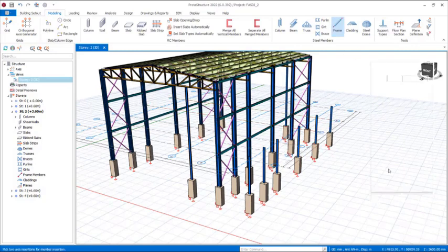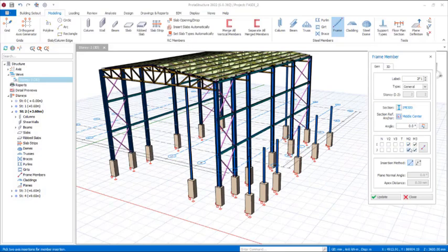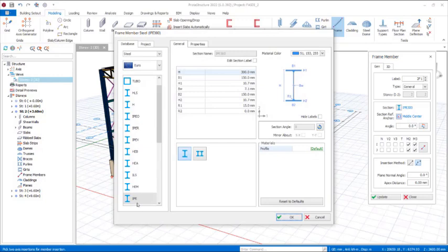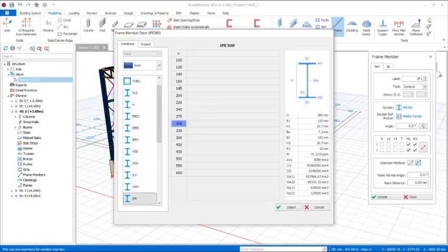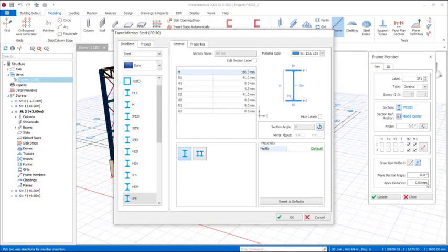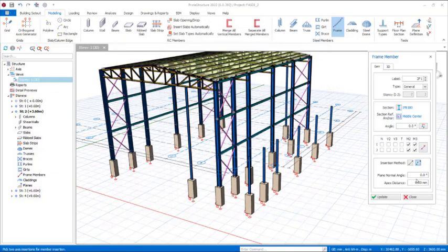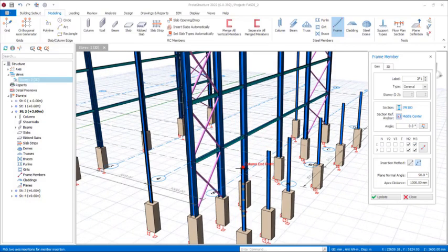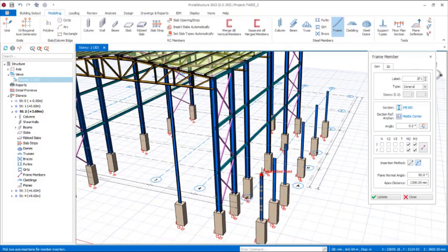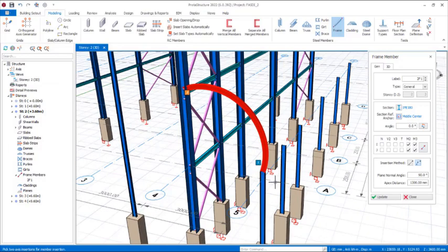All right, click on this frame and then come over here. Make sure you have all of these provisions checked, tick these provisions, and then you can navigate to the sections property. IPE 180. All right, click on this, select options, and then come over here, give it okay options first, give it an angle of 90 degrees. All right, for the apex distance 130, just like this. So after the settings are done, head your hand over the top of these stanchions, make sure you are on the top of this stanchion, click once and direct your hand towards these provisions, and then click to have your curved beam, just like this.